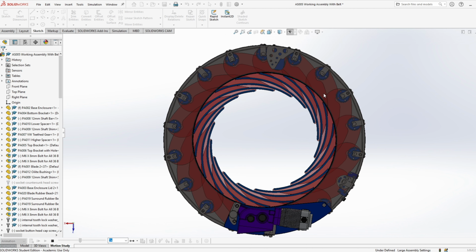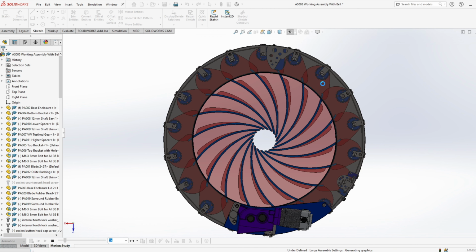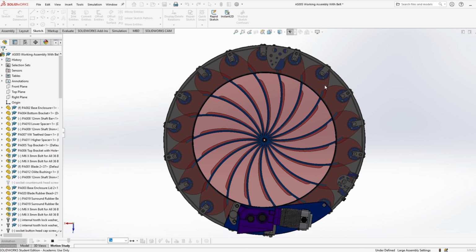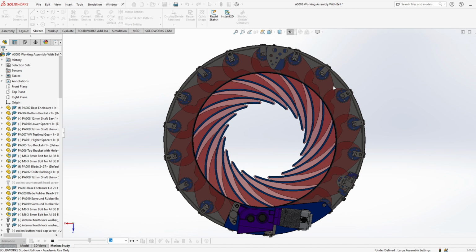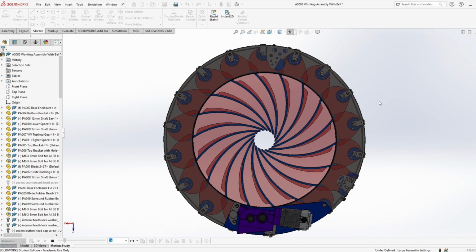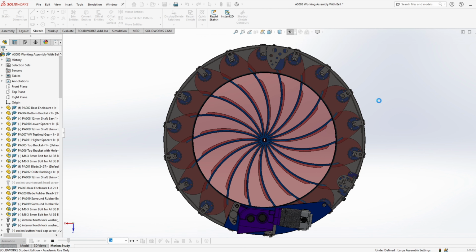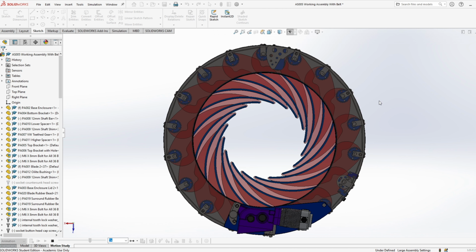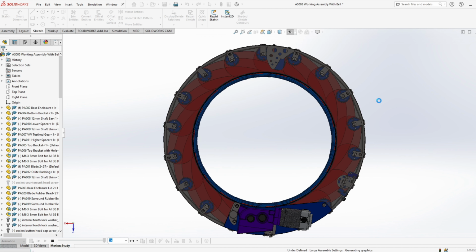If you remember in Prototype 1, each one of these blades had a square edge here, which caused a lot of binding issues with the neighbouring blades. If we think about this with respect to this demonstration, there would have been too much contact area in the dark red if the blades still had this excessive material.